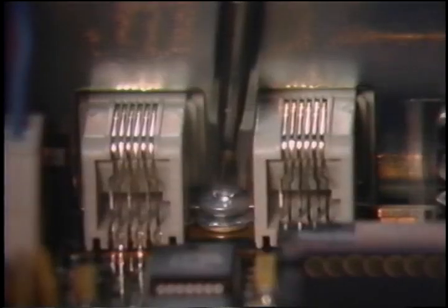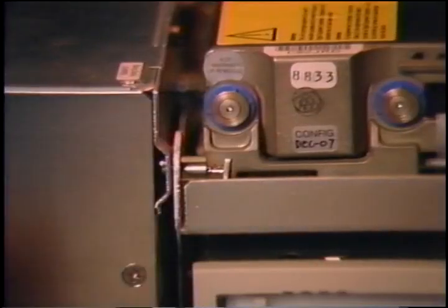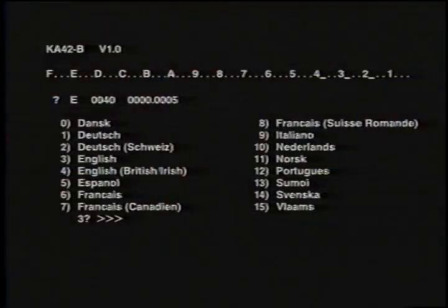During reassembly, when replacing the KA42, rear screw access might be tight. Ensure that the drive plates align properly. Confirm that the reassembled system passes its power-up tests. A status message for the time of year clock is expected.